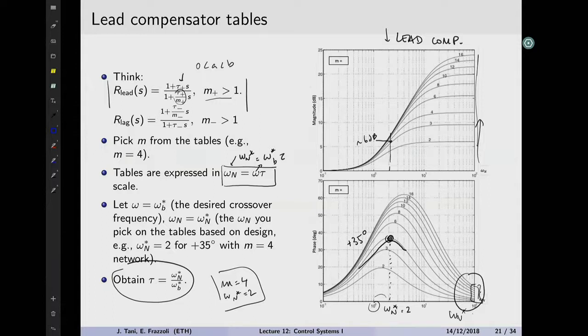If you remember, the transfer function between the tracking error and the reference was given by the sensitivity function, right? If you remember two classes ago, we said, okay, what are the steady state errors? They're given by the Bode gain, which was S of 0, basically.